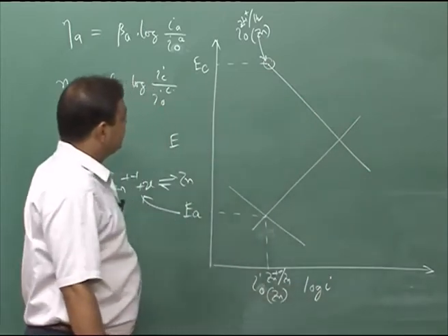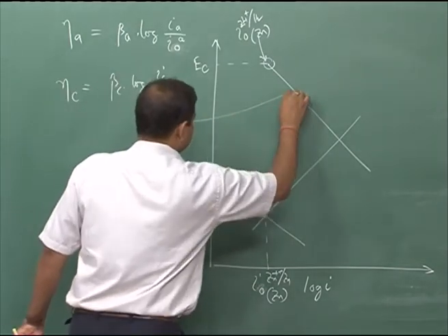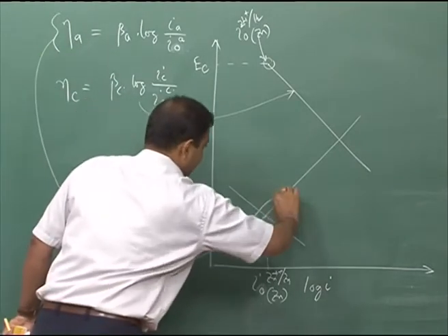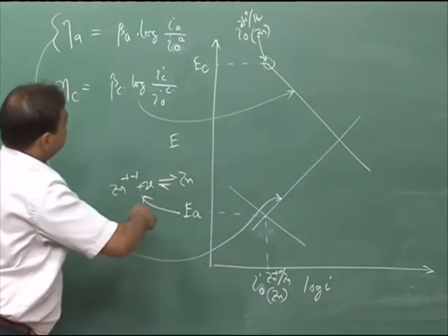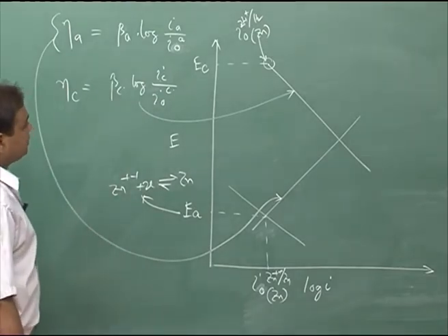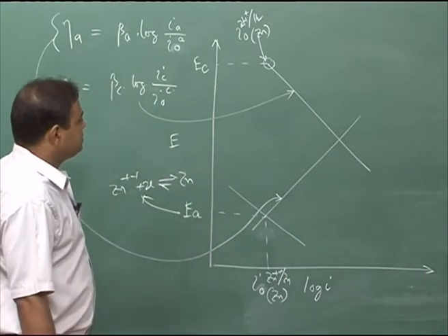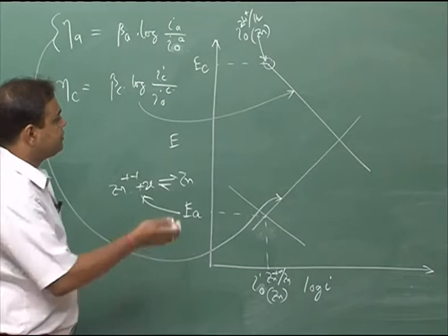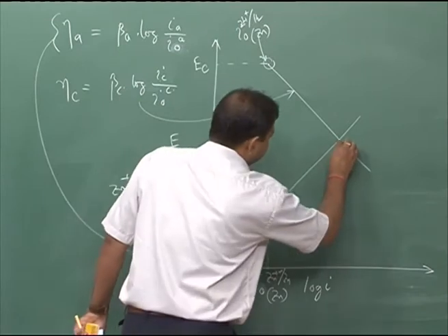This is the cathodic polarization, and this indicates this, and this one indicates this. So, the two lines are drawn from this concept of Tafel equation, and then if we have zinc dipped in HCl, the potential of the zinc will be at this point, which is the corrosion potential, because it will reach a new equilibrium state, and the corrosion would happen as per this